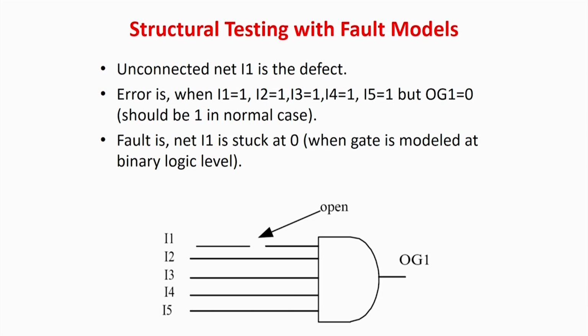So, what do we mean by statistical testing? Very simply, let me tell you. Initially we asked how you do a test, and you go for functional testing. Then you say that functional testing is very difficult, with complexity of the power n, etc. Then what do we do? We go for structural testing. But in structural testing you are testing only the gates and mainly the interconnects. Then if I integrate, how do you guarantee that the functionality is proper?